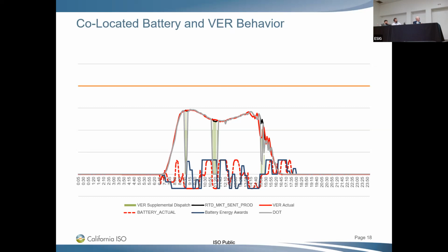So that you can see specifically in these instances, the market wanted the battery to move, and it needed to make sure it was honoring those point of interconnection constraints that were on the system. And so by doing that, it said, hey, solar, you drop down, battery, you move up, but I'm still going to hold the market at its POI, which was 100 megawatts. So you do see them working together very well within the optimization of the market, even though they are two single resource IDs.